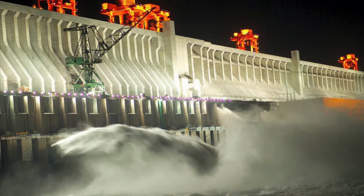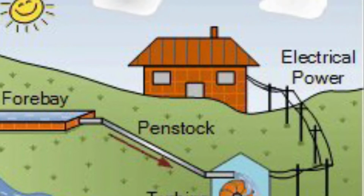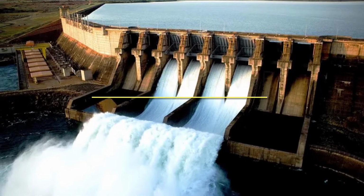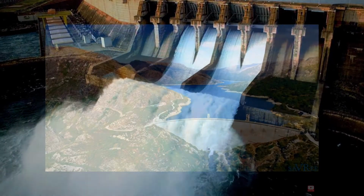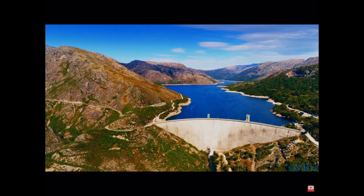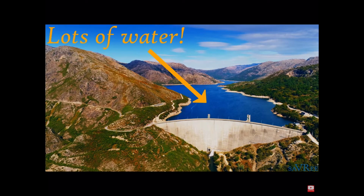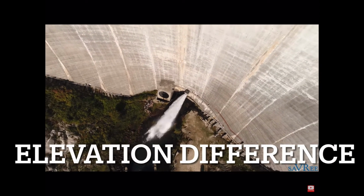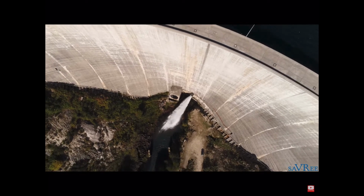That's right, some dams use water to generate electricity. These particular types of dams are called hydropower dams. Hydro means water, so hydropower is water power. To use a hydro dam, you need two things. One, an abundance of water, and two, an elevation difference between the outlet and the inlet sides of the dam. This difference in elevation is called the head.